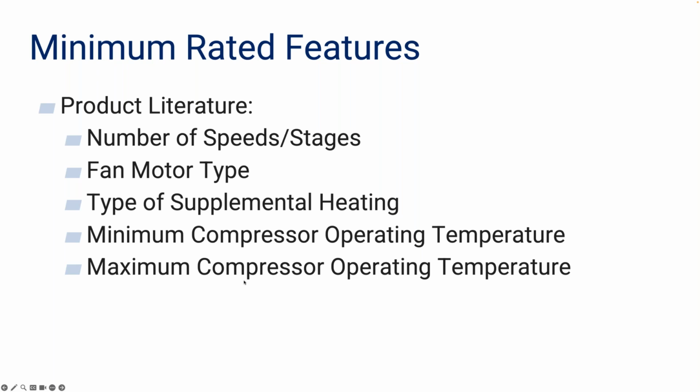The last one here is the maximum compressor operating temperature. Not all air conditioners are rated or capable of operating in some of the extreme temperatures that you find in the US. We included this originally, but I think we're going to remove it, because if you're not selecting an air conditioner that can operate in the conditions you're designing it for, that's a bigger issue than just a HERS rating.